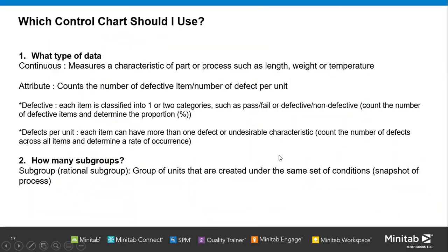Okay, so this is one of the things you need to know before you choose the right type of control chart. As we know, we go back to the basics. We need to know the type of data set itself, the type of parameter you're using. Is it a measurement, like length, diameter, weight, or temperature, where the measurement is a number? That one we call variables, or continuous data. Then we have attribute data, like defect or non-defect, yes or no, which is text data. It's a different term, but the same meaning. For attributes, it's text data, like a binary outcome.